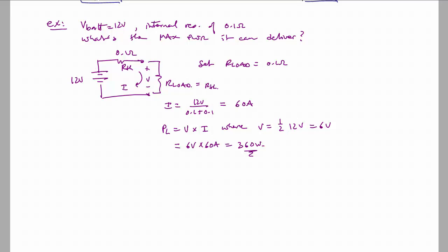So you'll have 720 watts coming from the battery, 360 watts going to the internal Thevenin resistance, and, assuming that load is some resistor, another 360 watts of heat generated there. Or if it's something other than a resistor, it's doing work, and it's ultimately going to become heat eventually.